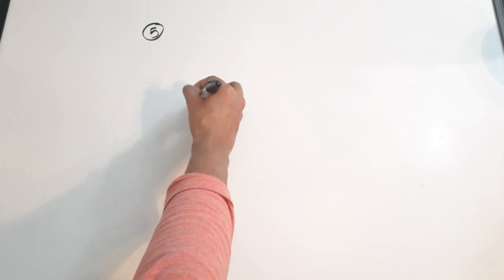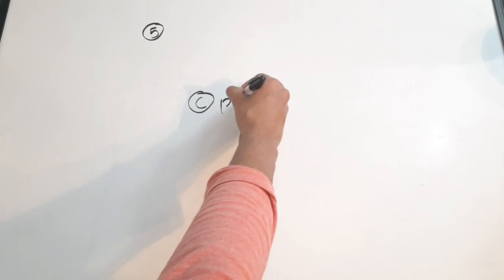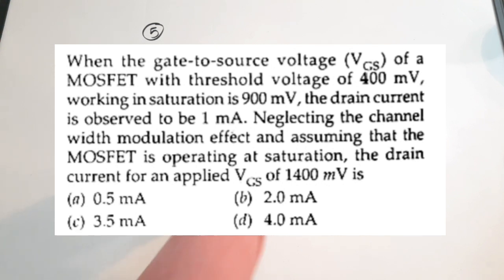You need to find what the power spectral density is for white noise. The noise at the input to an ideal frequency detector is white, then the power spectral density at the output will be parabolic. The options are raised cosine, flat, parabolic, and Gaussian. The PSD is parabolic, so the correct answer for question 5 is option C, parabolic.